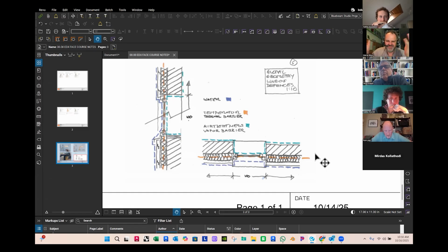I would say they stop because at the very end, your render on the inside, your gypsum board somehow does that. Or if you have a skeleton structure, there is a different film. Different story. Yeah. There's a film on the inside. It's a little different story. So therefore, the vapor line or the airtight line is then on the inside, making sure you gap all the various openings where the metal or the window frame joins the insulation layer or structure layers that you have filled, and then either taped.